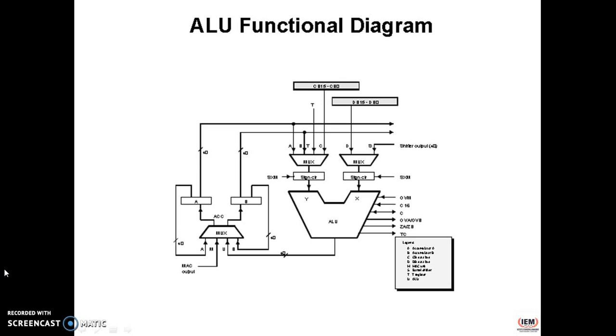The multiplier adder unit performs 17 by 17 bit 2's complement multiplication with a 40-bit addition in a single instruction cycle. In the C54x architecture, the 17 by 17 bit multiplier is present to give the ability to multiply a signed number by an unsigned number.